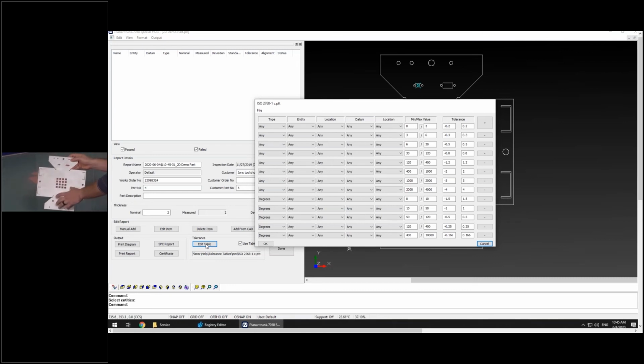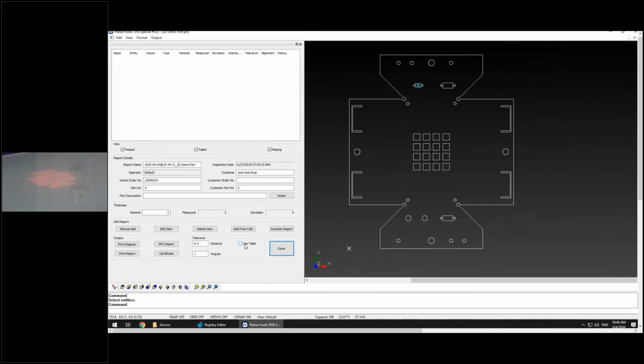And any internal features will be tighter because now it has to fit within each other, and those can be a different value as well. So you could use tolerance tables like that. You could also use a tolerance table to say, if you have a diameter that's a quarter inch or less, it has 5 thou tolerance. The bigger the diameter, the more tolerance you get. So then maybe you get up to 8 thou tolerance on 1/2 inch or more. Different things like that. You can use the tolerance tables to set up for you. And planar files can be saved with the tolerance tables, and then they can run that way as well. So you can use them if you want. Don't use them, but just know they are there and they are helpful. I've helped quite a few customers with those.